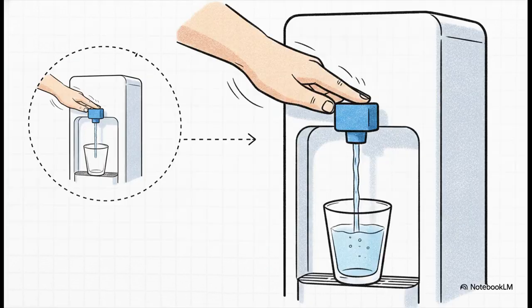Simple, right? If you're still trying to picture it, just think about a water dispenser. When you want a cold drink, what do you do? You push and hold the button, right? As long as you're pressing it, the water flows. The second you lift your finger, the water stops immediately. An A contact works exactly the same way. You have to actively push it to make things happen. That active command is the whole point of an A contact.